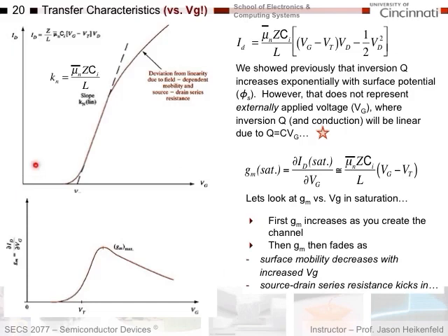If you do MOSFET analysis, you're also going to look at something called the transfer characteristic, which is how much drain current versus gate voltage. Look what's happening here. You get to the threshold voltage. I'm sorry, that should say VT here. So that should say VT.